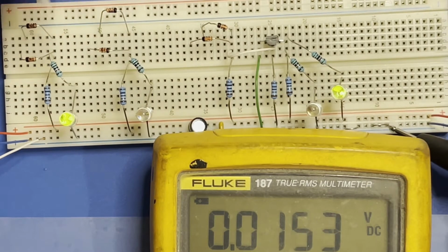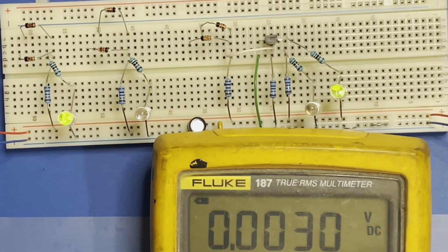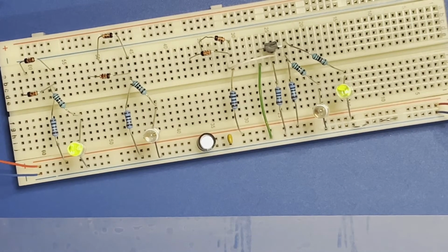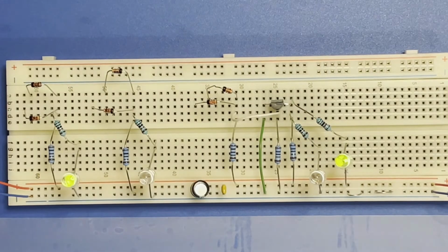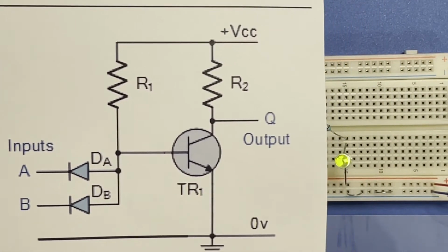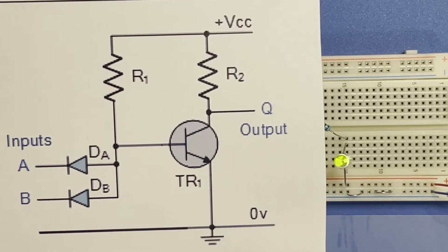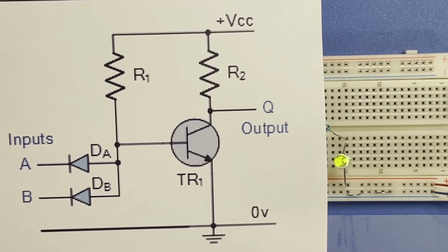To get nearer to real-world practical circuits, you need to add transistors to boost up the levels again and give current gain. So each gate can drive other gates. Now, that's where you come to this one. This is a Nand gate, as typically shown on the internet. And again, as a hypothetical circuit, that's approximately right.